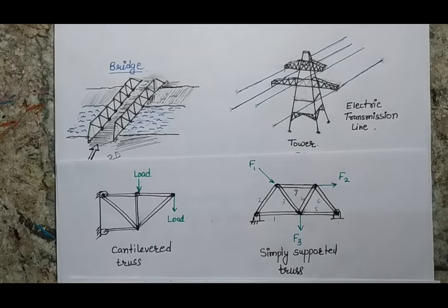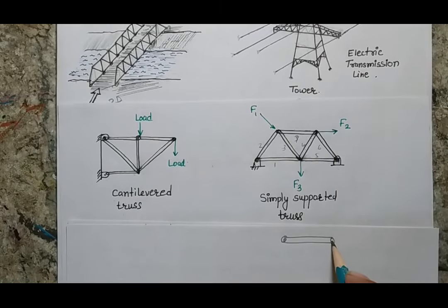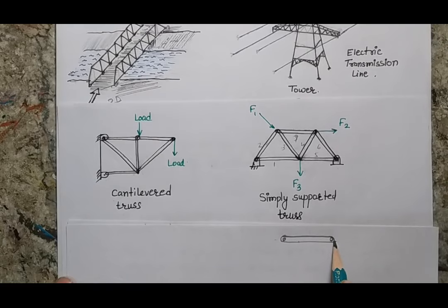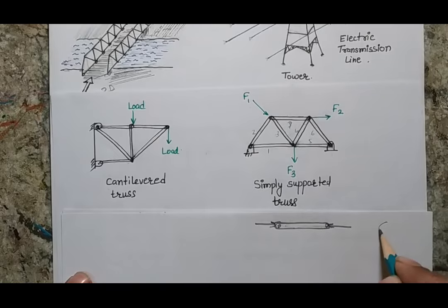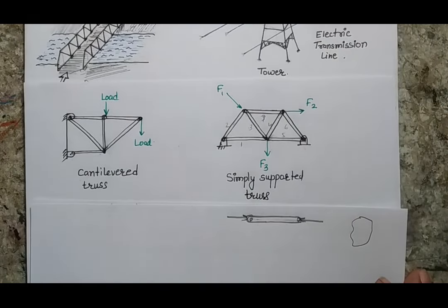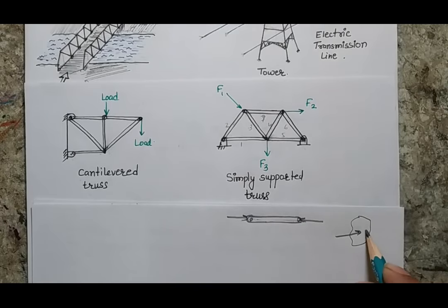and if we are connecting a body at the two ends with pin joints, that means there will be forces at the ends, and there will not be any moment at the ends. And if we have to satisfy the necessary condition of equilibrium of this individual member, the forces should pass through the axis of the member. Why? Because there is a basic law that if a body is to be in equilibrium under only two forces, the two forces should be collinear forces.